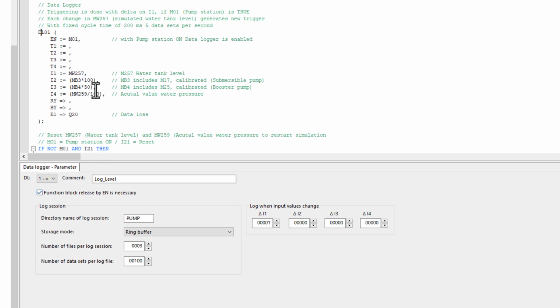is set to true. For this, the corresponding box for the function block enable must also be activated in the configuration of the function block. If this selection has not taken place, the data block is always enabled. The EN input is ignored.